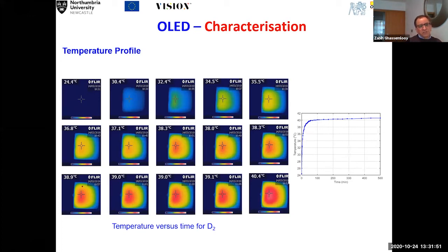So they are very cool and so on. So look at the distribution. This was for device 2, and you can see that really the temperature doesn't change at all. That's why they are very energy efficient, because they don't convert the energy into heat, they convert the energy into illumination or luminance level. And that's why they are 80% energy efficient compared to 37% fluorescent light and only 5 to 10% incandescent light.